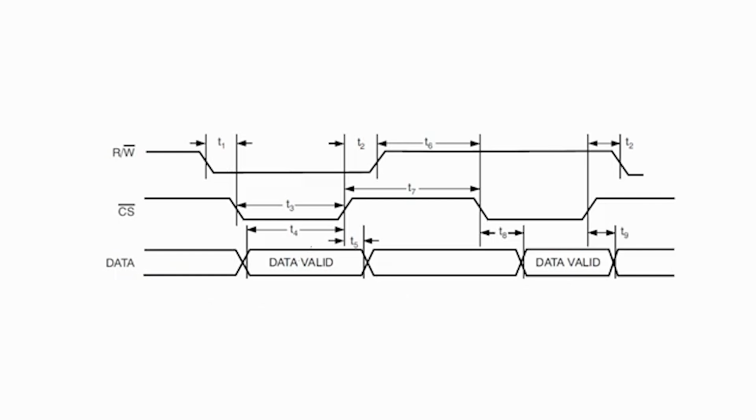Okay. So, we saw that chip select is an active low signal, correct. So, that is why when it is going low, the data is valid. That means data has been latched; till then the data will not be taken as valid data. Then write: when this signal is low, that means it is a write.